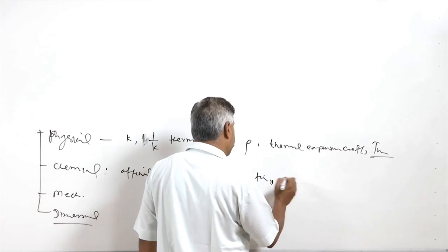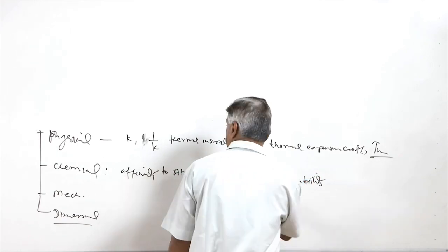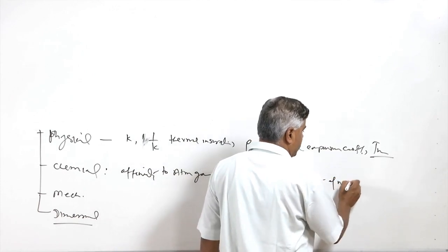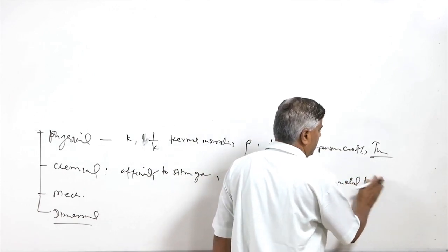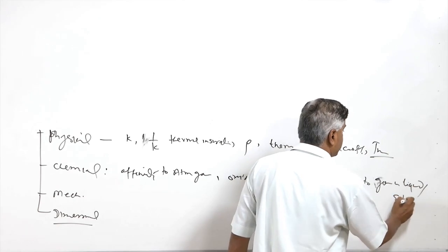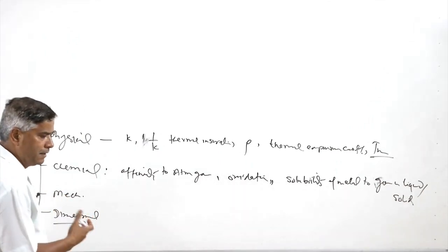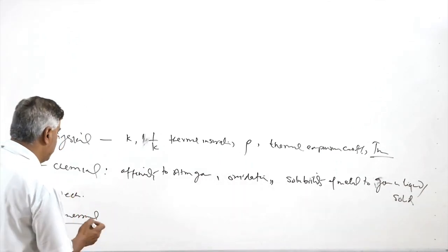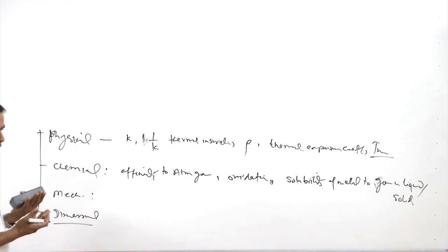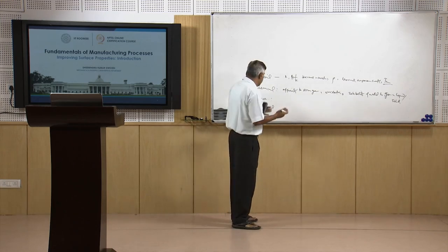Then there are other things which also affect the performance of the component, such as the solubility of the metal to the gases in liquid and solid state. Sometimes this leads to issues like the formation of pores and cracks due to hydrogen induced cracking or cold cracking.